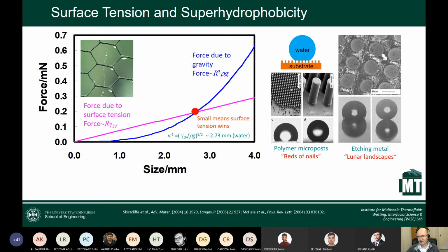And what I didn't know at the time was the undergrad went outside to have a smoke, and they used to over etch their surface. So it wasn't the surface shown in the picture there. The craters, this is a top view of copper, etched until they joined, leaving pinnacles just in between. And when that surface is made hydrophobic, you got a completely balled up droplet of water. The image from the side with the reflection. And so capillary forces dominating is very powerful.